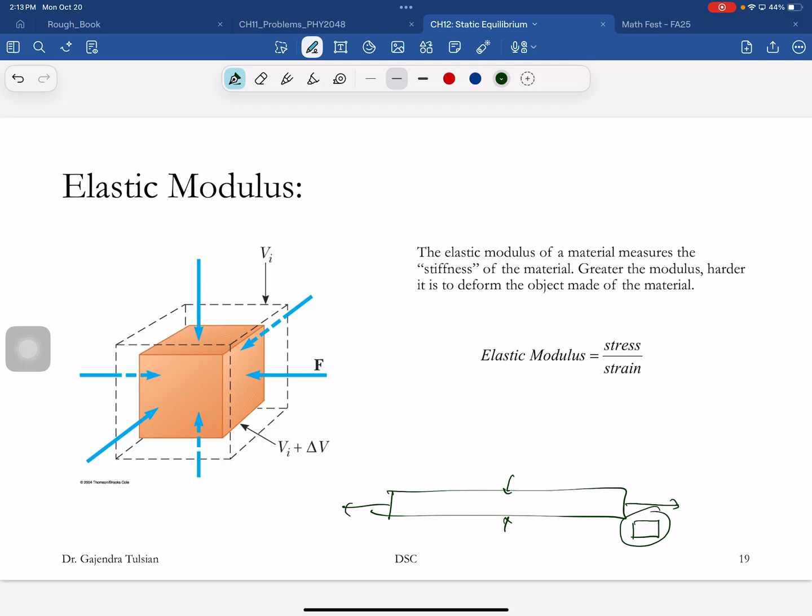Okay, so we look at that deformation. We look at volume deformation. Okay, and then here's the shear deformation that you see. So here's a structure, and you apply shearing forces, and the deformation is like that. For instance, when you bend down and pick up a weight, that's how your discs deform. And of course, you don't want your disc to rupture and stuff.